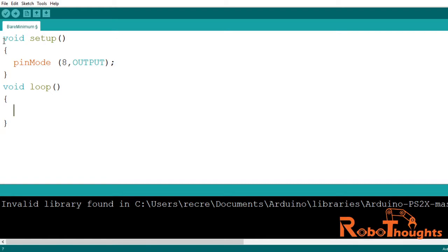Inside the curly bracket I am going to show you the function called digitalWrite. So how do we do that? D-I-G-I-T-A-L, digital, uppercase W, digitalWrite. Boom, there you go. You can see the color change, it becomes red. Digital write. And I am going to write to pin number 8 as on. So what do we do for on? It has to be HIGH, that is your 1.